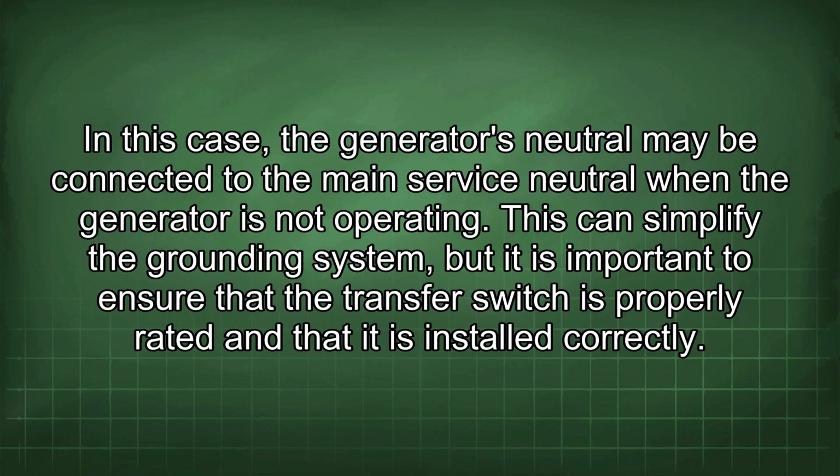However, if the transfer switch is designed to switch the neutral, the grounding requirements may be different. In this case, the generator's neutral may be connected to the main service neutral when the generator is not operating. This can simplify the grounding system, but it is important to ensure that the transfer switch is properly rated and that it is installed correctly.